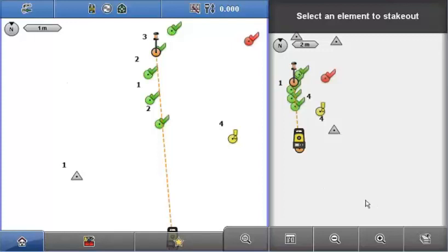In terms of other options, I won't run through them today. There's GPS, you can orientate to the sun, and also there's orientating to the last stakeout point, which might be useful if you're working in an area where there's no obvious site features. So you can find your next point based upon what you've just done.